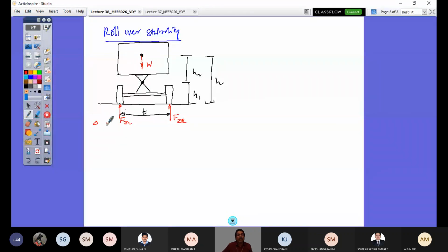The small r is the tire deflection. Let's consider that later. Now you can see the two rolls that I have defined. One is phi 1. Phi 1 is the roll of the unsprung mass. So what is that mass? It's the axle mass, the axle and wheel.